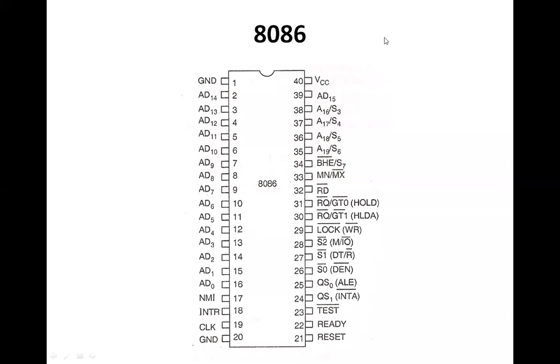So the next signal is the reset signal. The working of this reset is very similar to the reset used in the 8085, and the purpose is to reset all the operations of the 8086. So this is going to reset the microprocessor if the reset pin is high. Whenever any device wants to reset the operation of the 8086, it will put this signal high, otherwise it will work as normal.